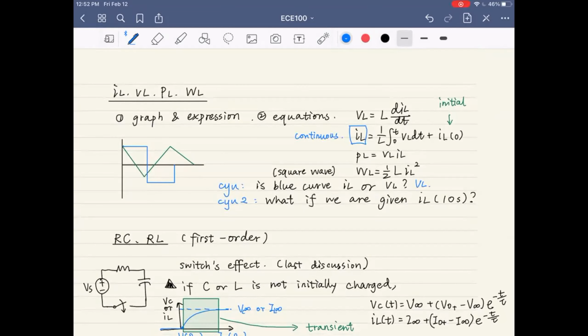The continuous property is really important because it helps you determine its status before the switch turns on or off. In such a short instant before or after the switch takes an action, the VC is continuous, so the time is too short for it to change rapidly.